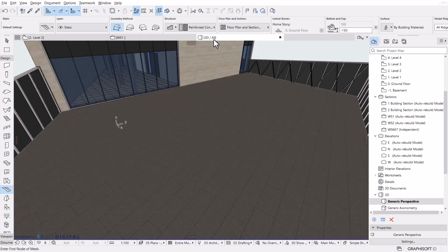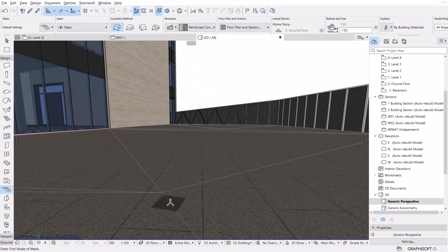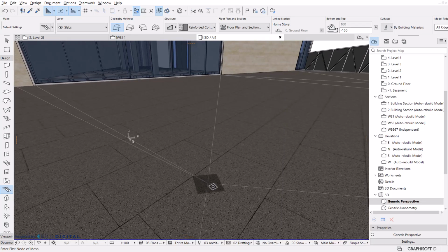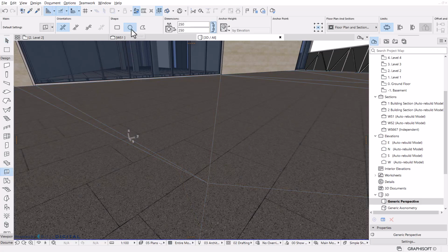Let's go to the 3D window, and I should be able to see that split acting right there. Now we're still missing one thing. We want to be able to see the drainage points and very likely create a little opening for that in there. So let's do that. Select the opening tool and set it to a circular shape, and then change the size to 100 millimeters. Now, let's get closer to the center of this and simply click right there where you have the node. That's going to create an opening in the mesh.